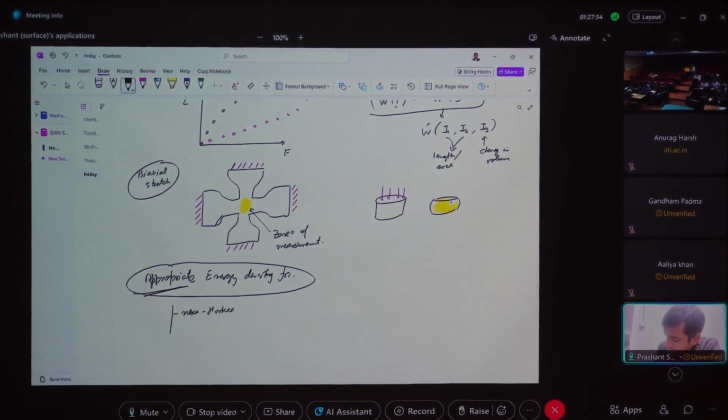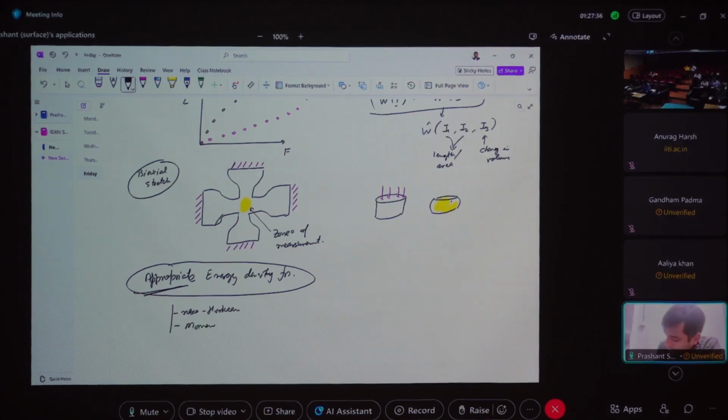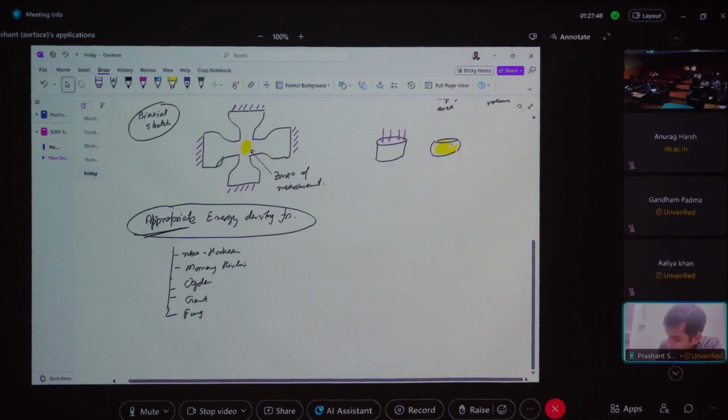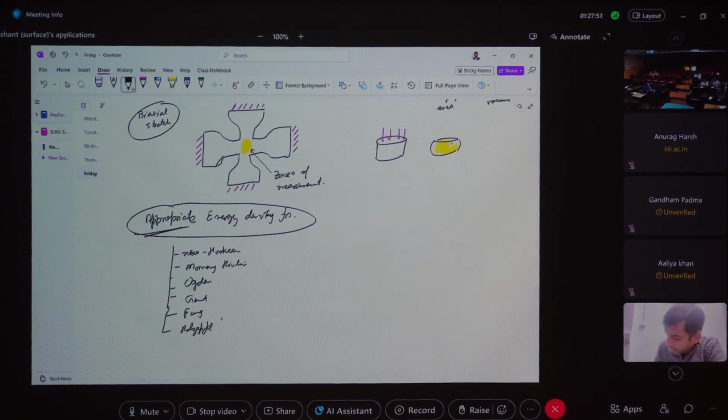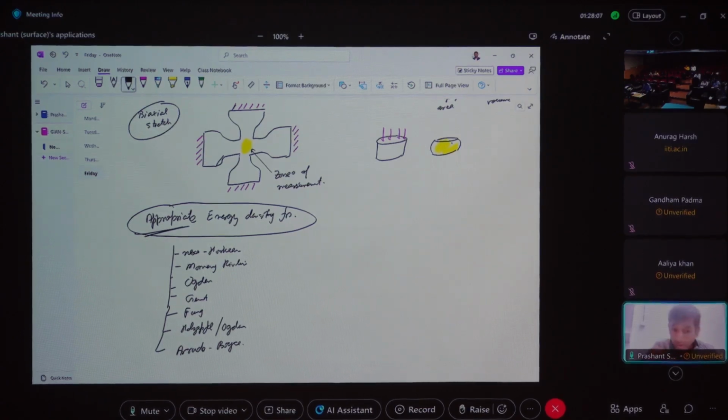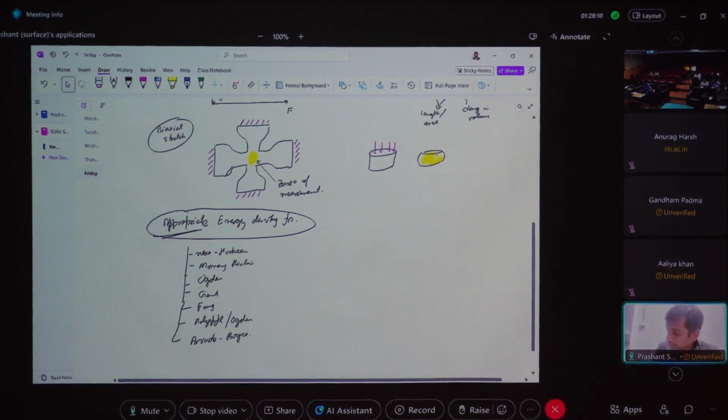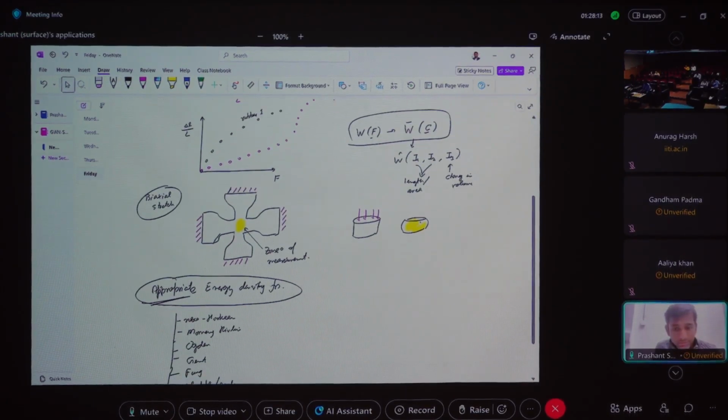There is Neo-Hookean, there is Mooney-Rivlin, there is Ogden, there is Gent, Fung. Then there are some new ones by Holzapfel, Ogden. There are some different types from Arruda-Boyce. And these are just some of the functions that I can remember off the top of my head just now. For rubbers, all for exactly the same materials, all for exactly the same experiments.